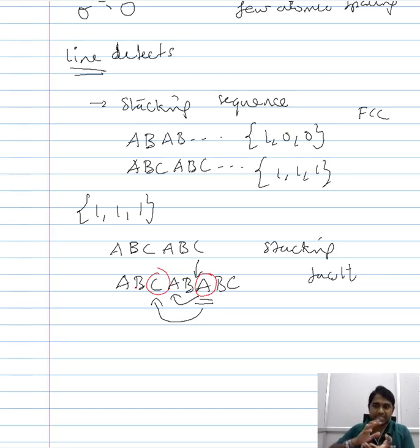What we observe is the change in the arrangement of the atoms in a particular plane, and this we refer to as the stacking fault. So now what we have done is we have moved away from the point defect, we have moved into the line defect, or a particular advancement in the line defect, which we refer to as the planar defect. Now this planar defect is possible for us to identify only when we know the sequence of the arrangement of the atoms based on a particular layer within a crystal structure. So we will build on this form of defect in the subsequent lecture.